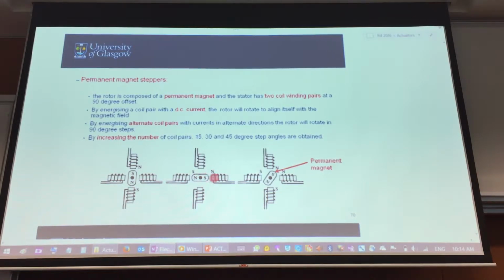The next step of that is to have, actually I prefer this picture to come in after this step. So you can see your north and south pole for your permanent magnet is always going to be the same. So in order for this south pole to start rotating toward the clockwise direction, what I'm going to do is to create this one as north and that one over here as north as well, shown in this figure over here.